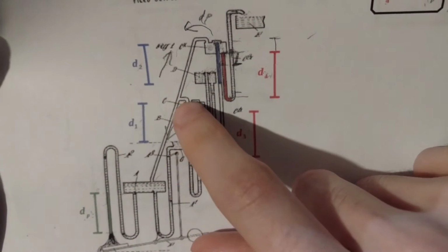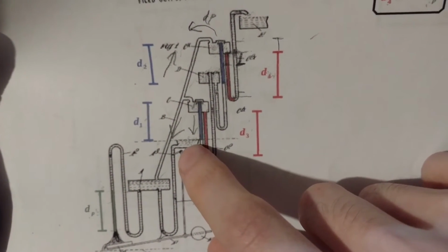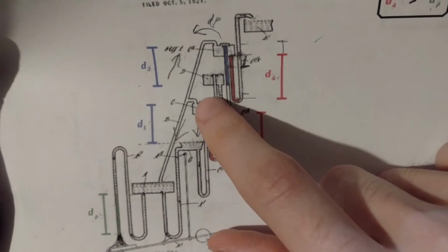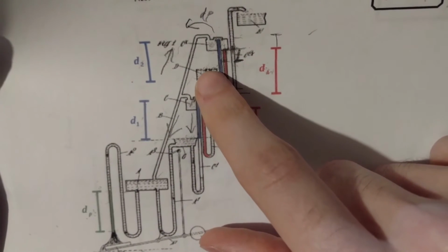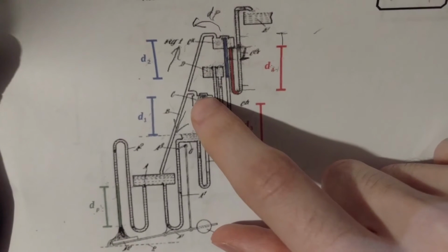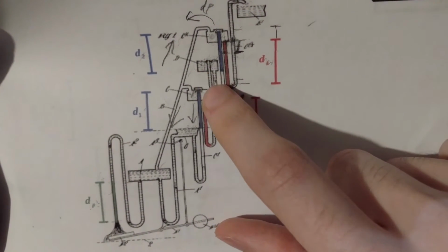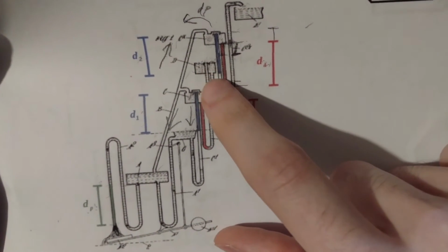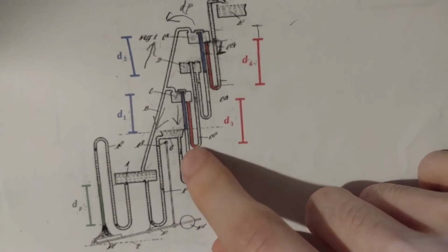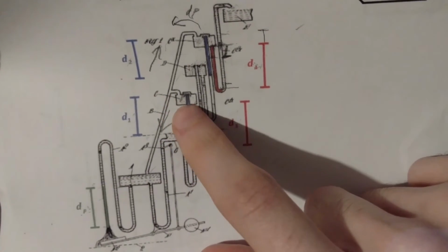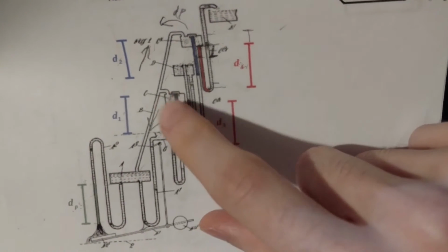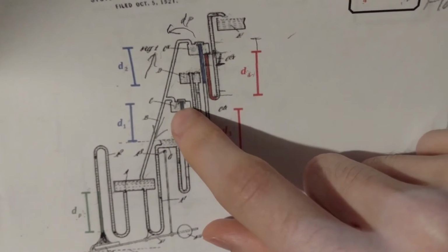Because when this thing's pulling, what will happen is it'll pull on the water in this tank here through that blue tube, but it'll also pull through the red tube. And since the red tube is directly exposed to the air, that negative pressure will be pulling that water up into here, and you'll have a little air bubble. Well, the air will start to fill up this tube from the top down, and if it's too much, it'll go past that U and fill this thing up and it'll become a living nightmare, believe me. It's not fun to deal with that. So it'll screw up your system. You don't want that air to get into here.